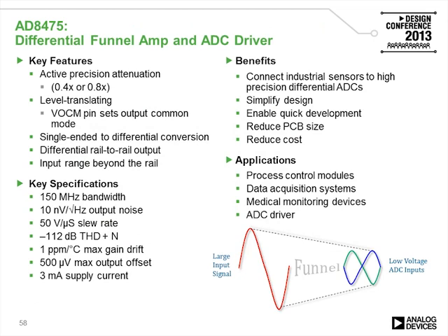The AD8475 is a differential funnel amplifier and ADC driver. The advantage of this amplifier is that it can take the regular and most common plus and minus 10 volt single-ended signals and convert them into a differential signal that can fit into the input range of a modern ADC.